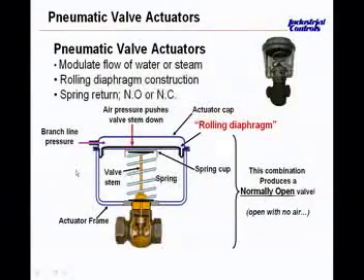On the maintenance side, John, we've talked a little bit about before, just to share what your experience has been, that these bladders that we talked about here can be easily replaced on a lot of these devices where the top can open up and unscrew out, right? Exactly, yeah. The wear parts, of course, because the diaphragm is in continuous movement, the edges will eventually crack, they'll dry up, so it's not a real big deal to remove the top and replace the diaphragm.